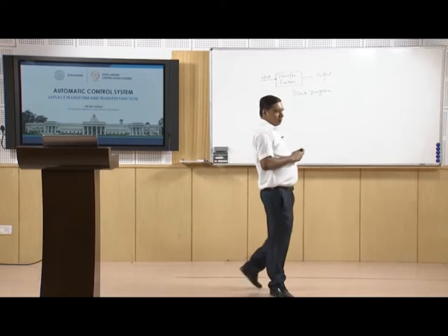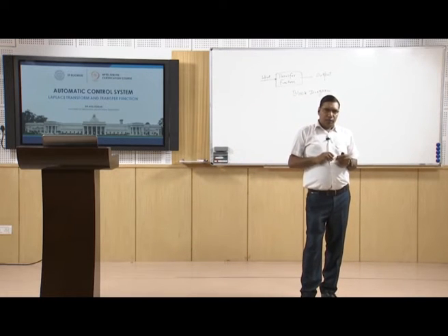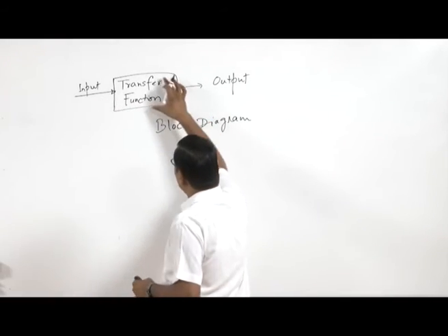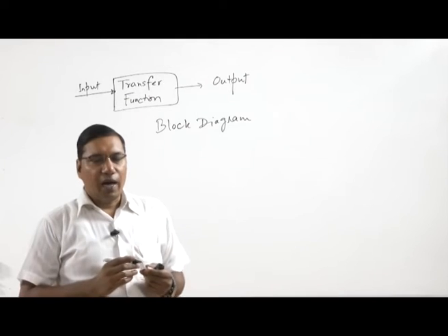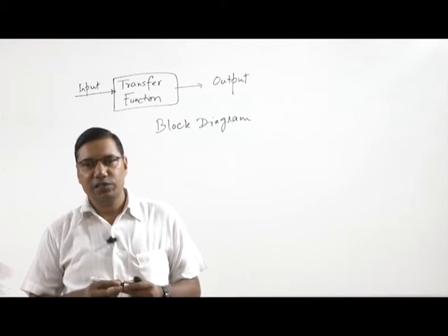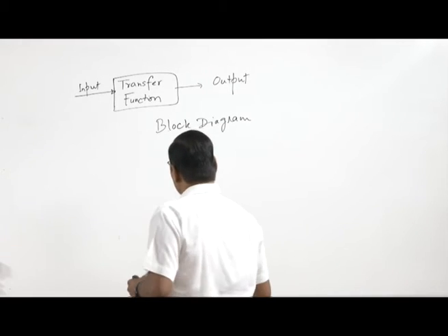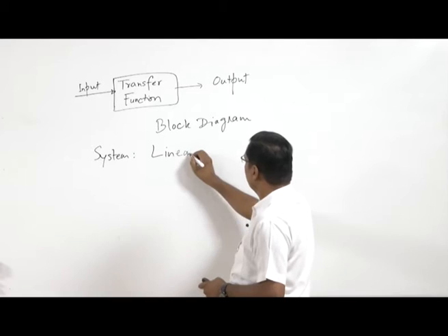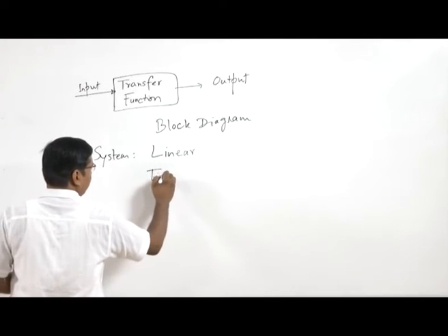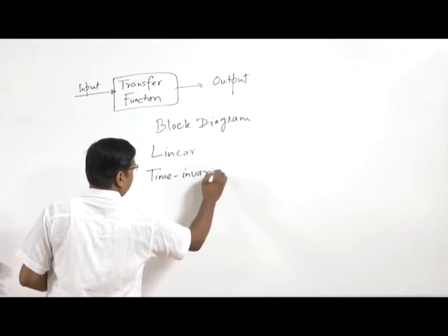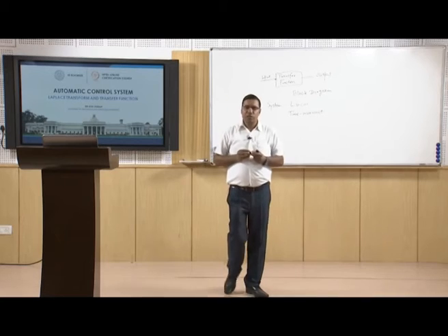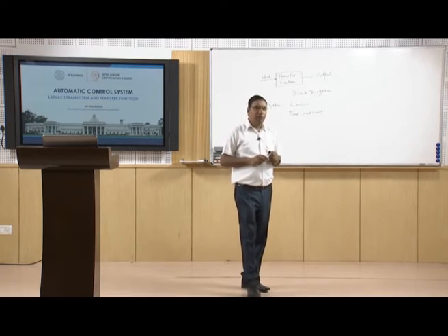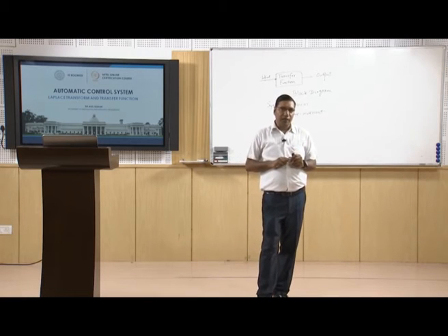These transfer functions characterize the input output relationship of any system, and they are valid only for linear time invariant systems. So the differential equations that represent the system should be linear, and the parameters of the system should not vary with time.